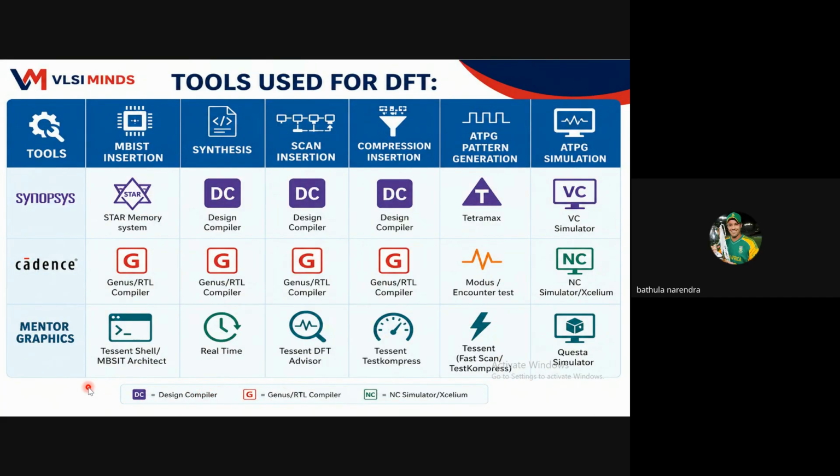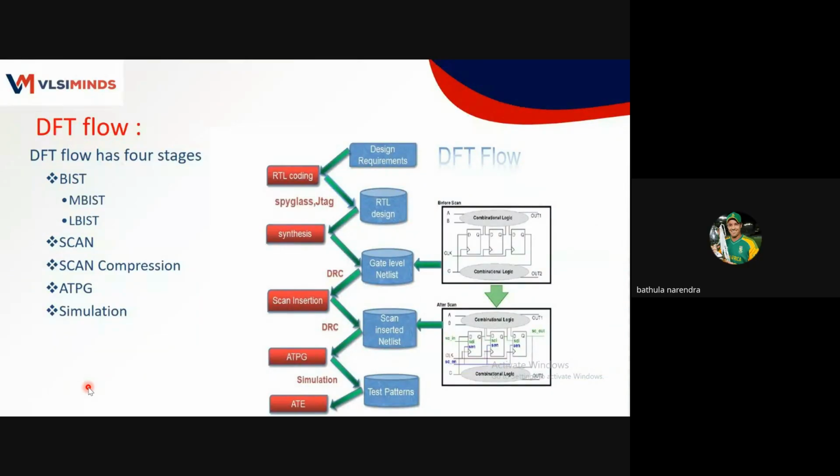Hi, Satish. Regarding LBIST, for a SoC, how much can they target, percentage wise? If we have any memories, then we'll go with the MBIST. If we have logic related to the gates, all those things will be targeted with the LBIST. So the percentage, 80 to 90%, we can get the test coverage.